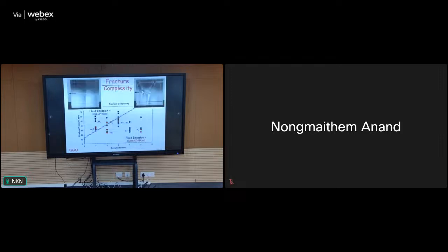We certainly know that in static gas fracturing, in some respects, the complexity of the fractures is influenced in a big way by the fluid which is used. One big distinction seems to be between the use of subcritical and supercritical fluids. Supercritical fluids, such as supercritical CO2, nitrogen also, are capable of giving quite complex fractures at relatively low breakdown pressures, and so might be favored over other liquids and other subcritical gases which might be used in such a system.